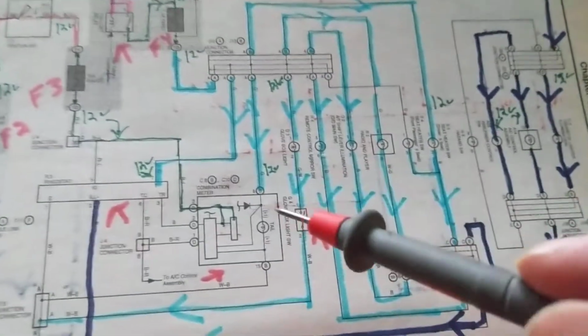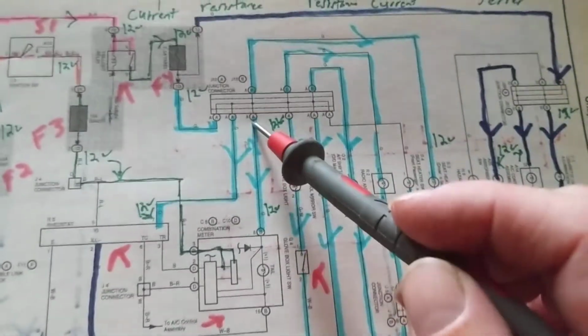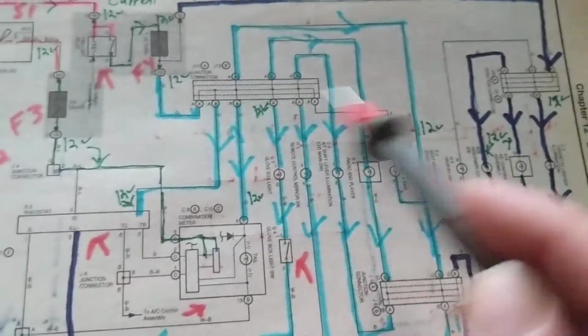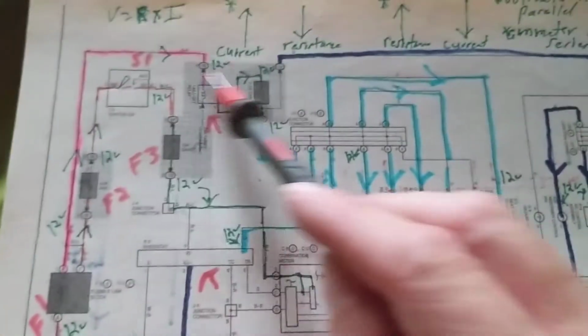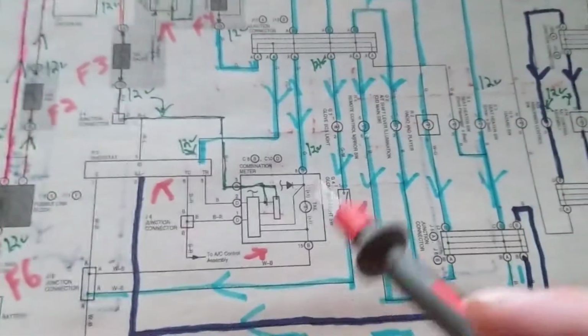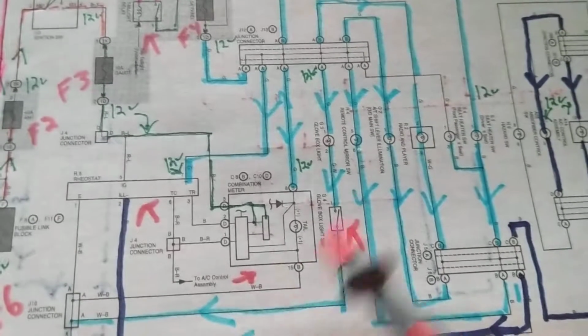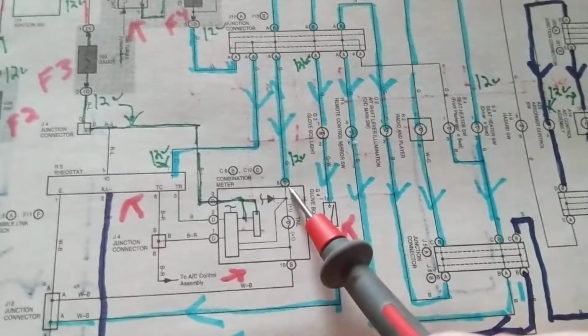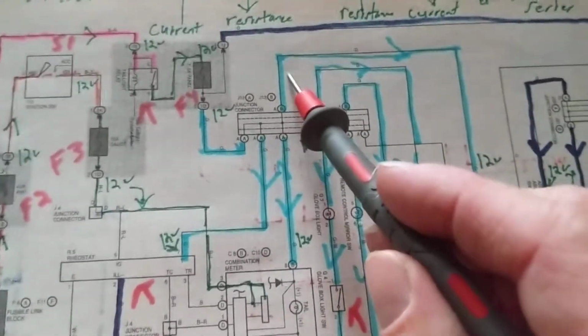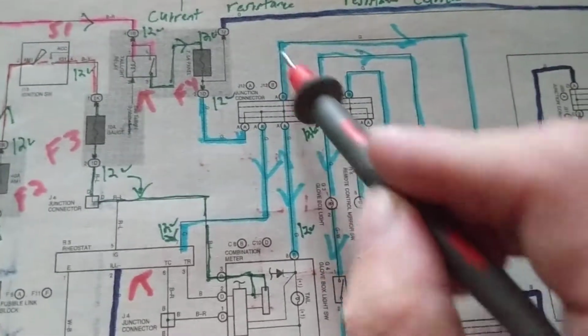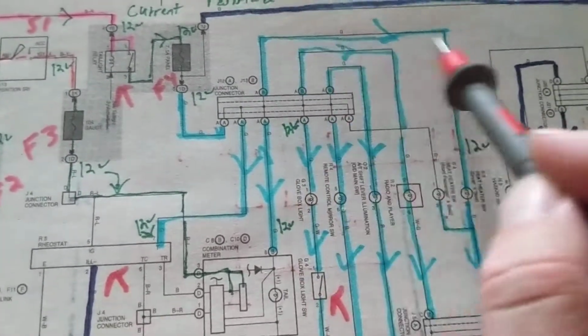And I made so many videos on how to interpret. Remember, when you look at a schematic, you have to go up sometimes, back, this way, that way. You do not always start from the battery, like I pointed out so many times. If I have a key component that I'm working with, this module, and I'm supposed to have 12 volts, then I backtrack and see where it comes from. That means I have to go back, not necessarily always going forward in a schematic.